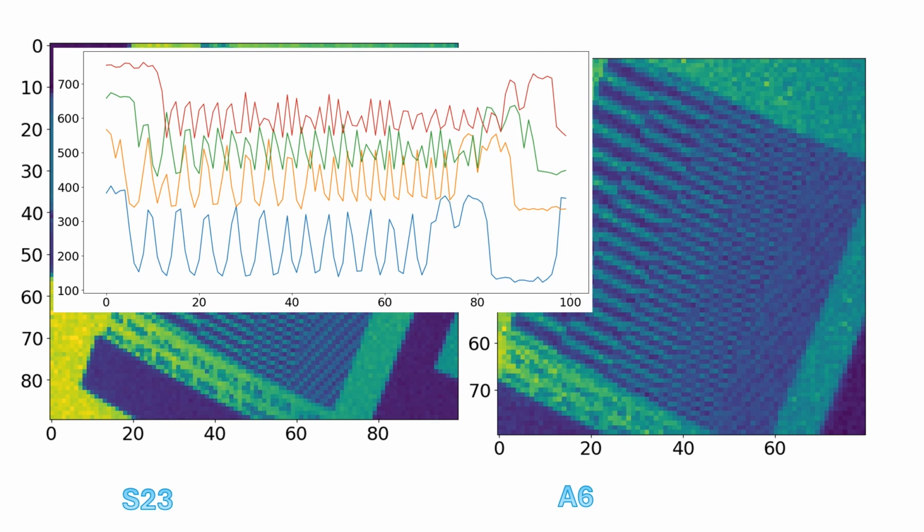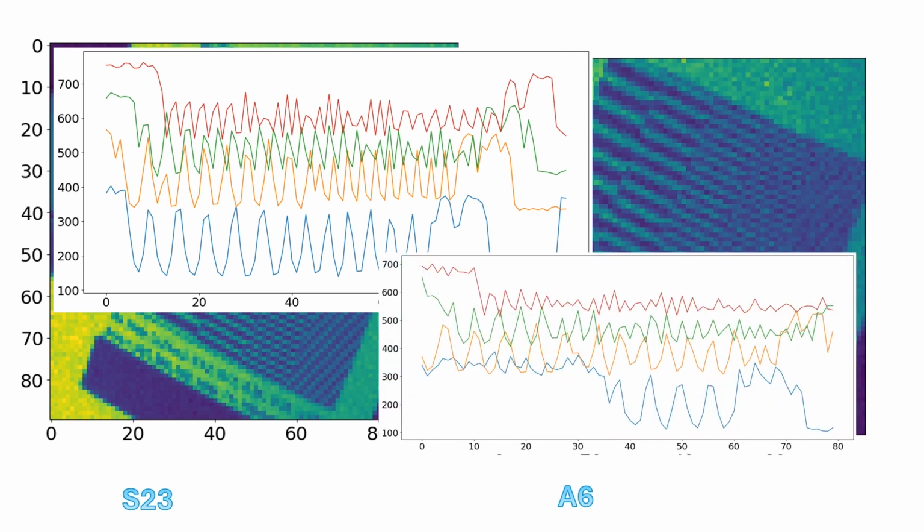But the blue curve at the bottom is a plot through the low frequencies at the right of the image, and then as you go up, we're shifting over to the left of the image, and then shifting to the right and going to higher and higher frequency parts, and you can see that the range of modulation is decreasing as we go to higher and higher frequencies. And at the right, you start to see also some aliasing at the high frequencies. If we compare this with the tablet, as you go to the high frequencies, basically the frequency modulation is lost and the signal becomes constant. So you can compare response just by looking at what happens with resolution charts.